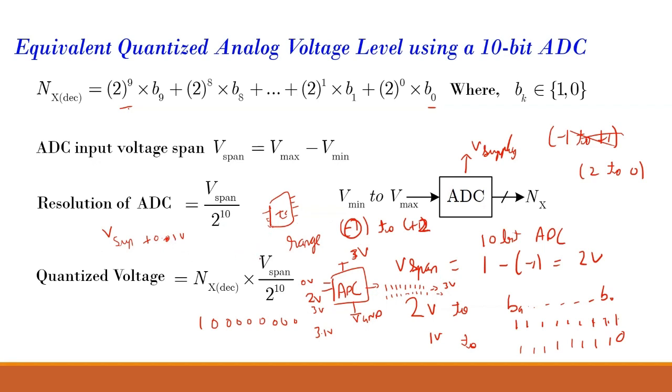So that is why, when we are choosing the ADC, we must make sure that the input to the ADC lies within the supply range. Okay, so supply defines the permissible range, not the input. So my supply defines what my permissible input range to the ADC is. Sir, suppose in this case the supply voltage is 3 volts and we give 2 volts at the input at the maximum. Then will it take any intermediate digital value or 111?